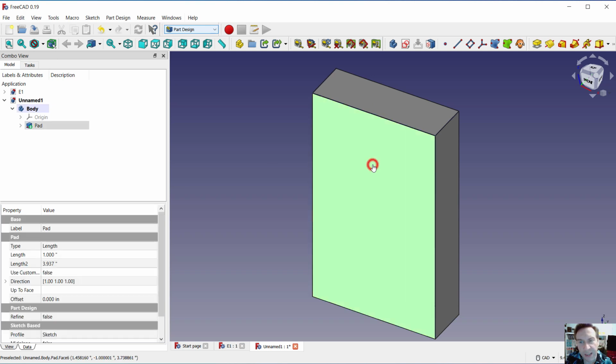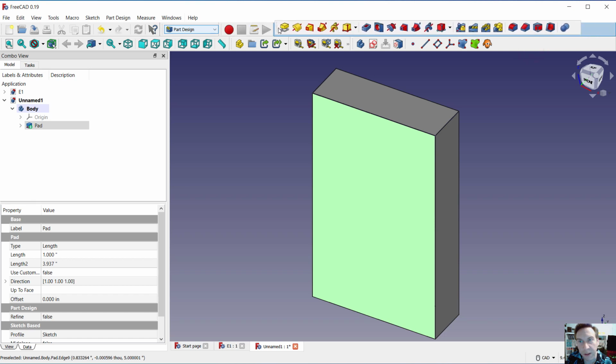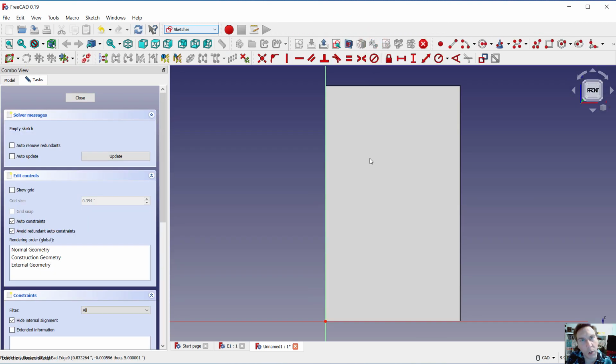All right, now go ahead and we could select this face, and we're going to start a sketch on it. So right now my sketch tool seems to have disappeared, but over here, if we click over here, actually we might have to drag some of these out to better position them. There it is. So what I'm looking for is create new sketch. So select that, and it will bring us normal to the surface. You could sketch on any planar surface, i.e. flat surface. Or you could sketch on those planes that we had earlier.